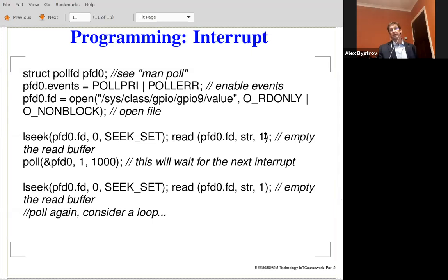After that, the buffer enters the state when it is waiting for new data, and then this function poll is applied to the same buffer. What it does, it causes a delay. Basically, it starts and sits there waiting until new data has arrived. After waiting is finished, it will read basically one character into this buffer, and this number corresponds to the emergency situation.